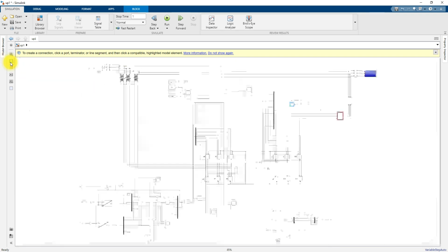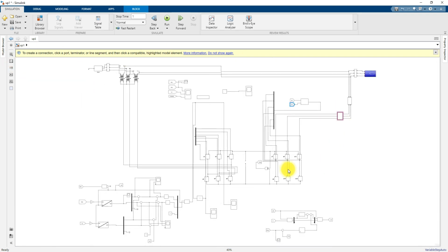Okay, so this filter will eliminate the harmonic problem because of this nonlinear load, right? So it is going to change the nature of the source current. Okay, so this is a DQ control we are applying in both the series active power filter and the shunt active power filter of the UPQC.